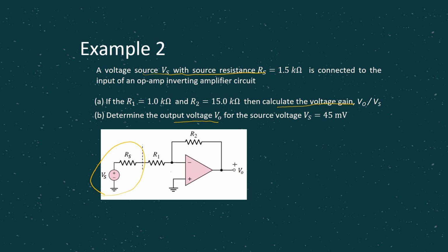It's the same concept where you have to know the two main characteristics. V1 equals V2, right? As you know, here it is grounded, voltage is 0, so automatically here is also 0. Another thing is, whatever current is flowing at the input, let's say I1, will be the same current going to the output, because there is no current going into the op-amp.